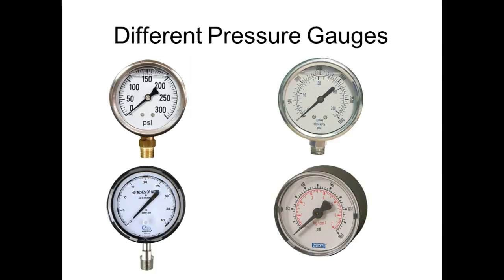But if I run it at 70 PSI, then I'm decreasing the mean time between failure, because I'm running it above what the seals and everything are rated for. So what we do is we have pressure regulators. I would set my pressure regulator at 60. Your pressure regulator has a gauge on it that shows you the pressure where you regulate, and your compressor might have a gauge that shows the span of pressure it's operating at. Does that make sense?